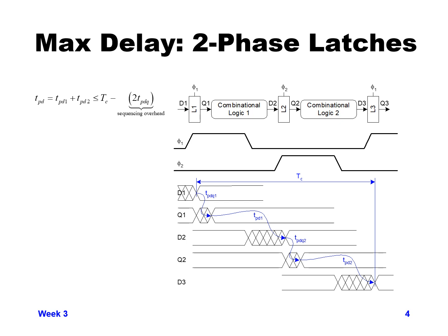If you go back and look at inverting latch versus non-inverting latch, we might have basically one pass gate and one inverter to go through for an inverting latch, which can be relatively quick. So you can see how two-phase latch design has some advantages over flop-based design as far as delay goes.